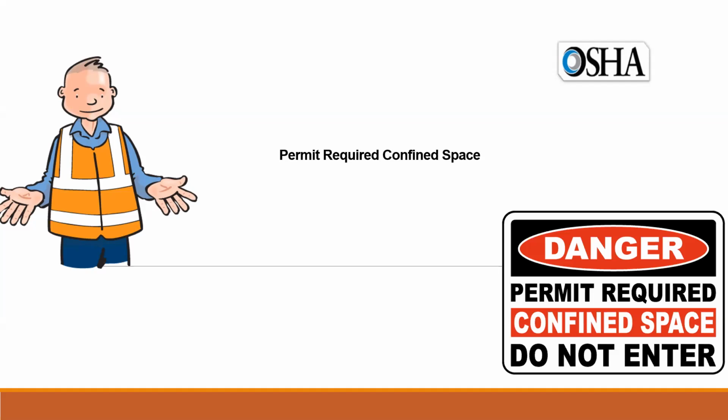And also sometimes the conditions require it. For example, when you start the work it was a normal condition, and after some time rain started or some storm started. So in this case, we need to immediately hold our activities and review the conditions in our permit again, and then we will issue the permit.